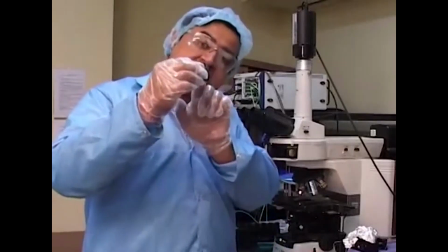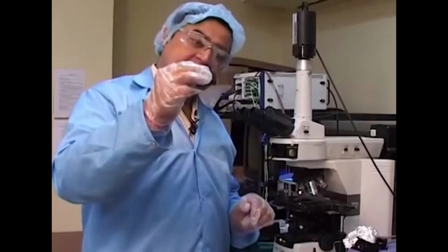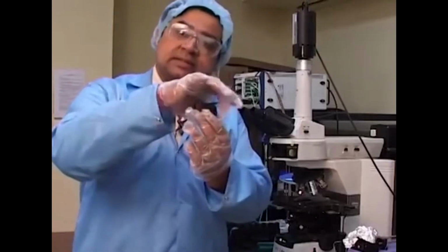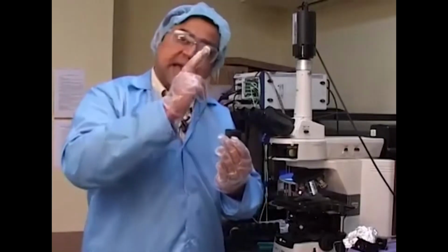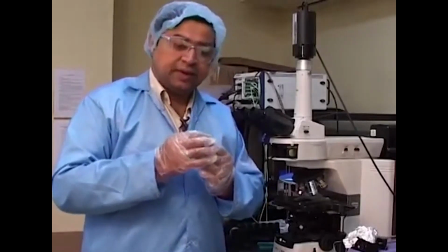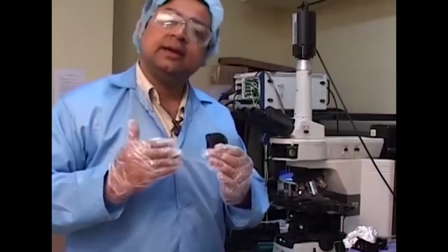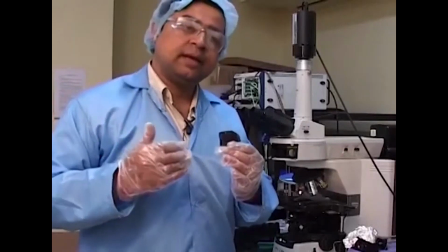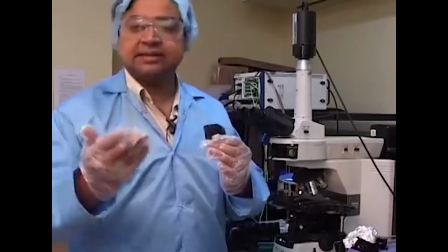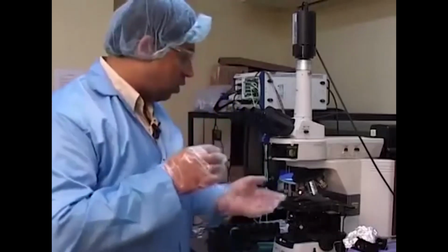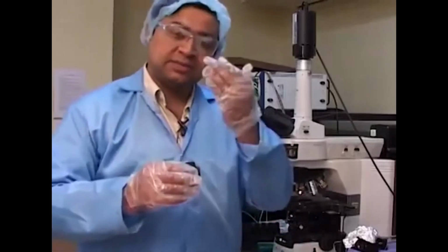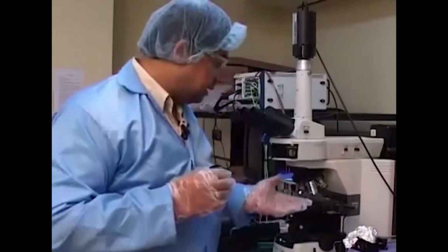So, what we use is this principle of filter cubes, and essentially we just remove the filters from both ends. Therefore, it is just plain light which we are looking at for exciting, and whatever is reflected off is captured, and essentially we can design the dichroic mirror in a manner that it gives only the visible region of the spectrum. Okay? And so, typically we can see a mixed coloration, probably white light, which is reflected off the surface of this wafer, and which comes out and gives a good feeling about what the image is on the particular sample.